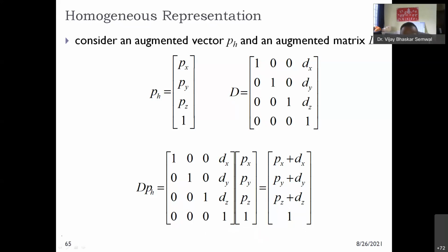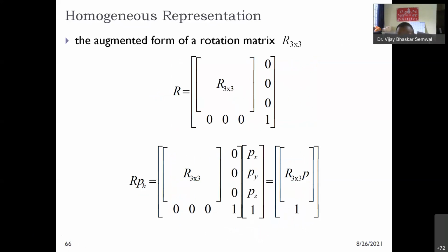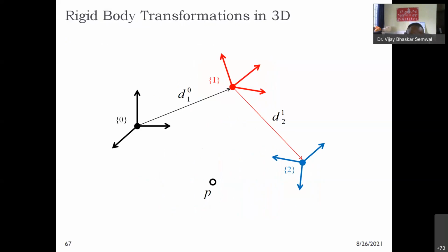So almost you have learned translation and rotation. You have merged the things, so now you can do it easily. Very perfect, I have seen the answer, Dr. Manjula. That is correct. So now what is happening? The first 3 cross 3 matrix is rotation. The last 3 cross 1 column is for displacement. You multiply. If you just want a rotation, you make the displacement 0, 0, 0.